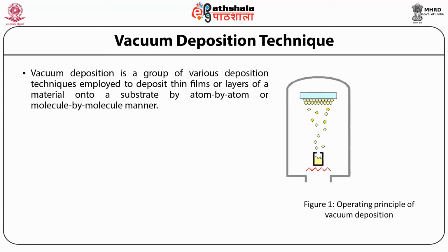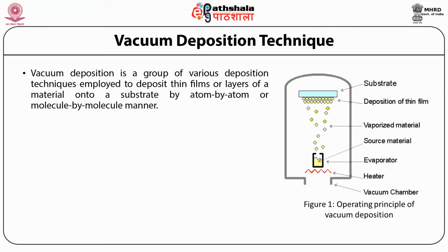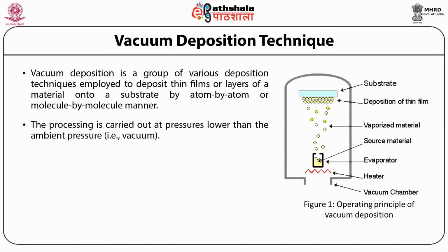Vacuum deposition is a group of various deposition techniques which are employed to deposit thin films or layers of a material onto a substrate in an atom by atom or molecule by molecule manner. The processing is carried out at pressures lower than the ambient pressure, that is, in vacuum.